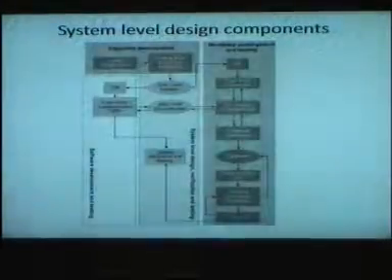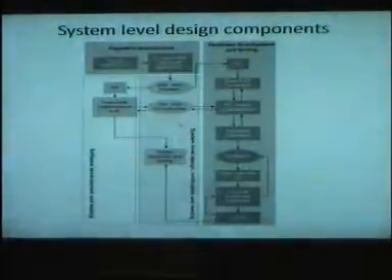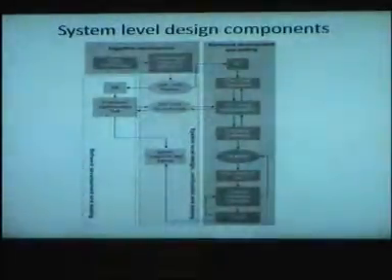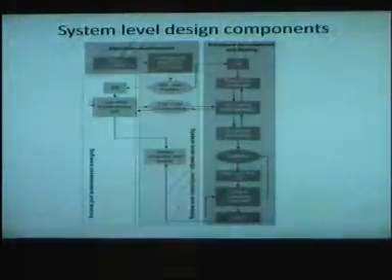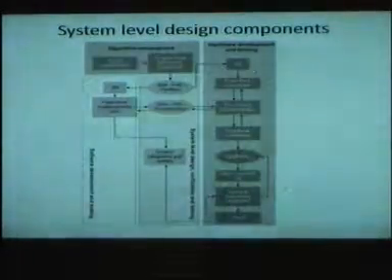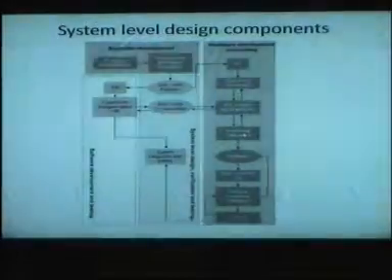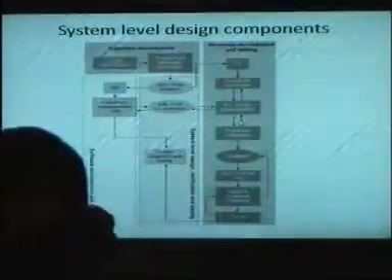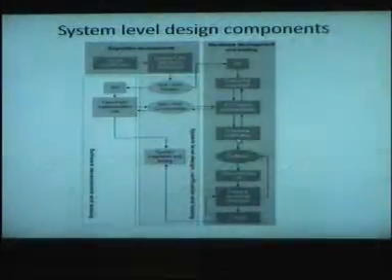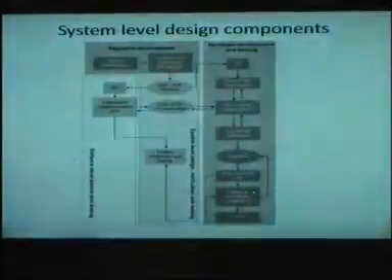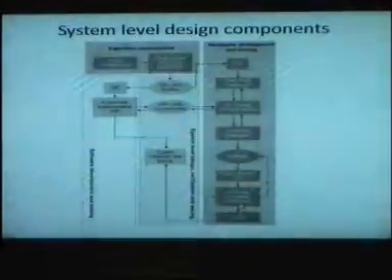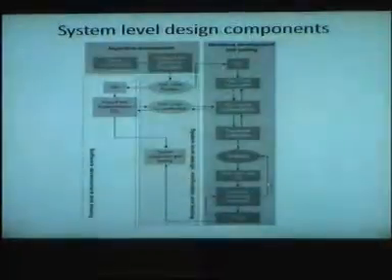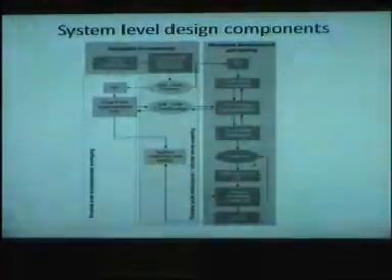So we'll adhere to those guidelines as well, and we do software hardware partitioning. Usually a team of engineers is porting algorithms in software, and others are designing hardware for those algorithms. Going through this route, you take the algorithm, convert it to fixed point, code it in RTL Verilog, do the functional verification, do the synthesis, generate netlists, do the timing, and see whether you're happy with the timing or not. If not, you either redesign or resynthesize, changing the constraints.